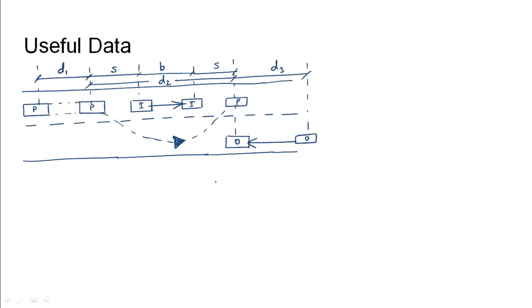So when we talk about overtaking maneuver on a two-lane two-way highway, we can see that there will be a passer which intends to pass the vehicle at the front, but it is not able to pass since the vehicle is traveling at a slower speed. So sometimes what they do is they will slow down to a speed equal to the slow moving vehicle's speed, and they will travel for a reaction time of TR. This is because they may not be getting a clear gap in the opposing traffic stream. So they will travel a distance of d1 with a speed of the impeding vehicle's speed, that is the slow moving vehicle, into its reaction time.